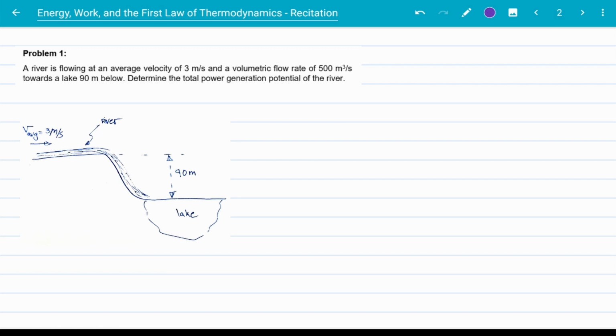of this river? Now first we need to find a location to put our turbine that will generate the highest power. Now take note that the turbine is a mechanical device. Mechanical devices convert the mechanical energy of a flowing fluid directly into power or work. Now the equation for mechanical energy of a fluid is actually the mass flow of the fluid times its mechanical energy per unit mass, which is kinetic energy plus potential energy plus pressure times the specific volume of the fluid.